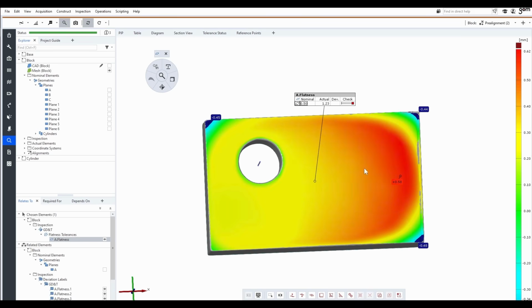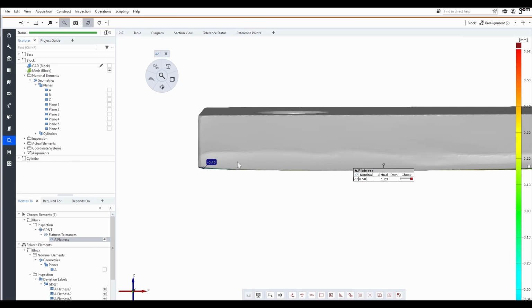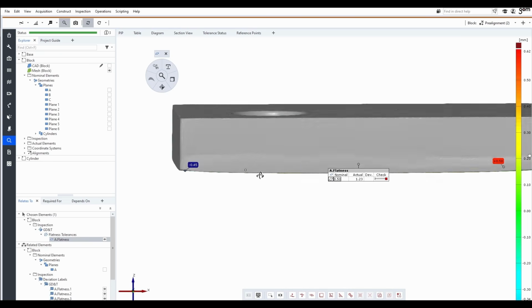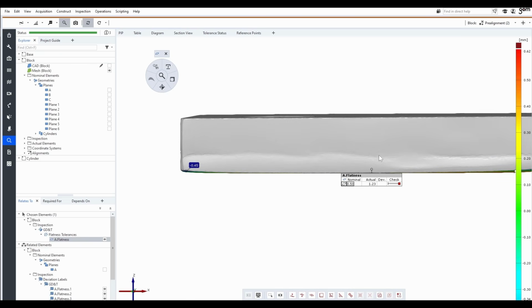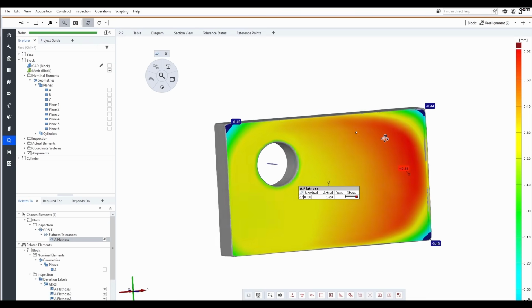So you can see that it lifted up here in the corners, and that makes sense. This is a 3D printed part, and if our bed adhesion wasn't particularly good, the corners would lift up during the printing process. And that also explains the sort of wrinkling you've got on the side here, as all that plastic was just kind of piled on as the printer went over it.